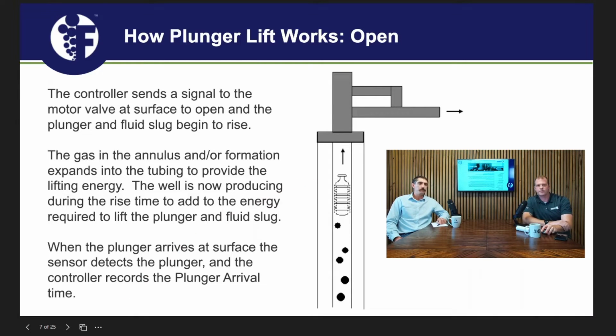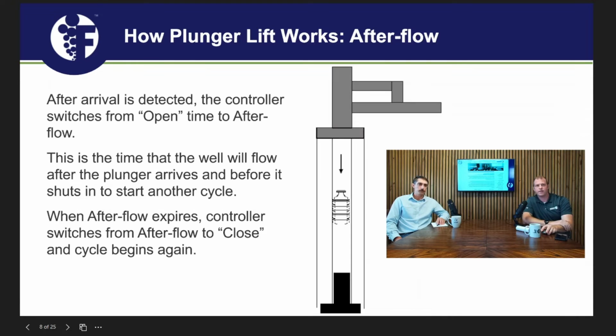Okay. Perfect. And so after the plunger's arrived, that arrival sensor tells the controller, hey, plunger's up at surface. Yes. And then we go from there into what we call afterflow. Afterflow, depending on the style of plunger, it could either stay in the lubricator or it could start falling back down, right? My preference, this is where it could get a little bit subjective.